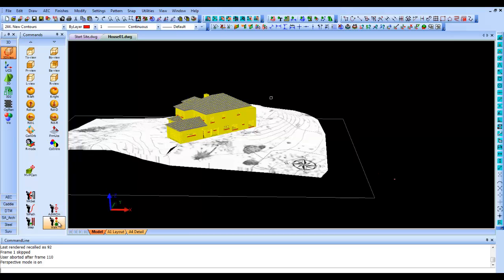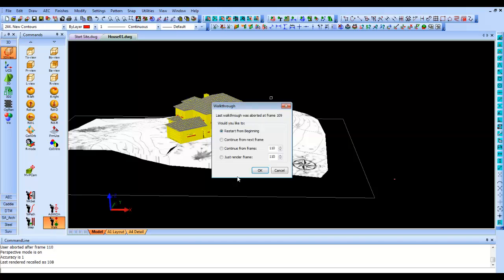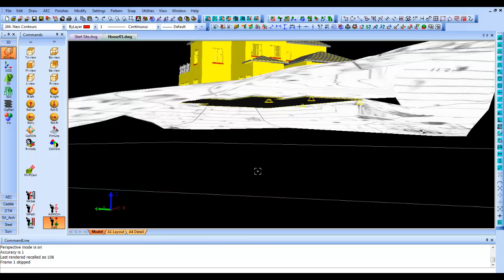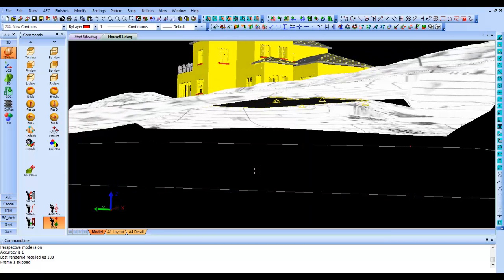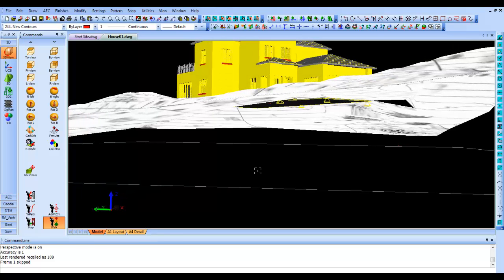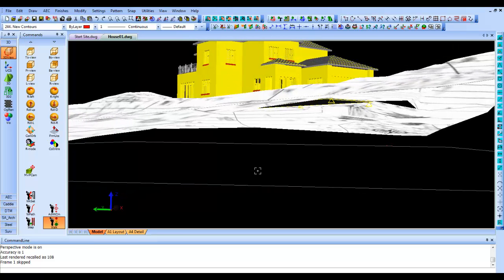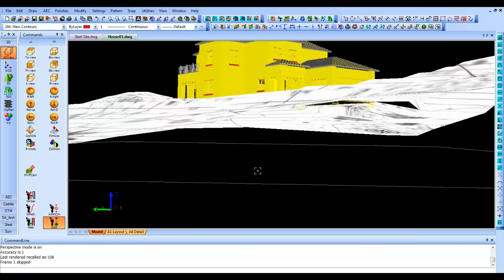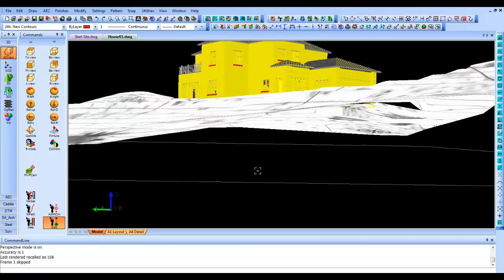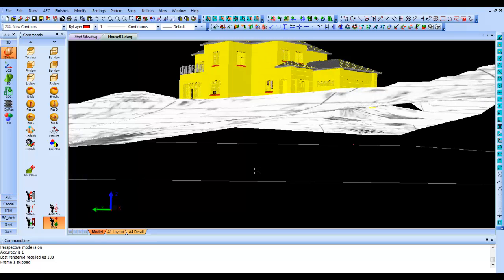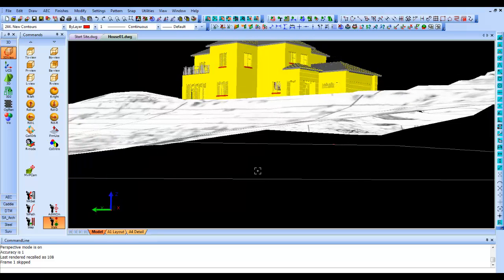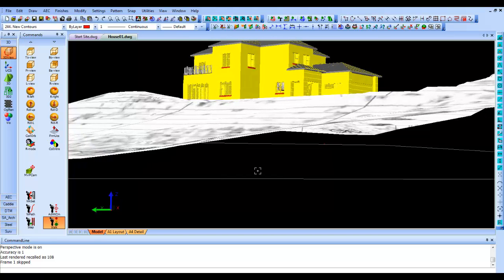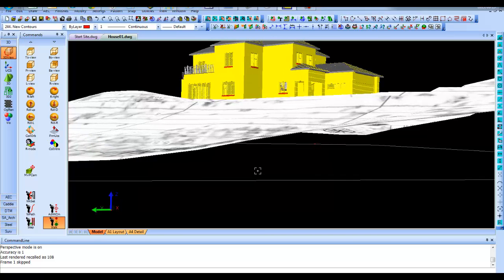In conclusion, we've created a fairly complex drawing from a mere picture. We inserted the picture, we traced the contours, we entered the text for the heights for those contours, and then Caddie traced those contours for us by transforming them to the height positions of the text placed next to them. Then we asked Caddie to convert those contours to 3D points, and we convert those 3D points into a tin model by the Delaunay triangulation algorithm.